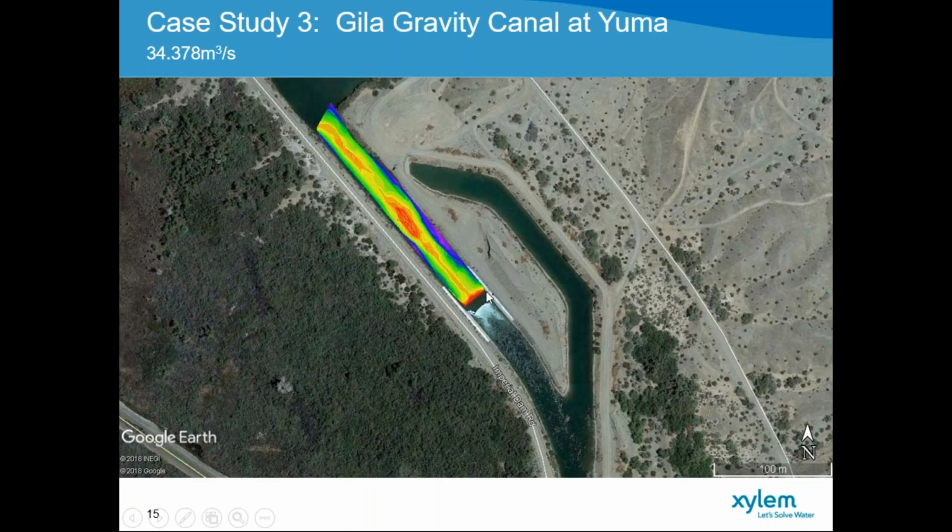During the bathymetry survey using RiverSurveyor, we also performed velocity measurements. This is a velocity contour plot in the channel itself. Here you can see the velocity distribution upstream, and then you get an acceleration across where the shallow portion is, or where the actual cofferdam was located. Then you get a reduction in velocity and even very slow negative velocities on the edges due to the deeper pool present downstream of it, and then again an acceleration right at the notch of the gauging weir.